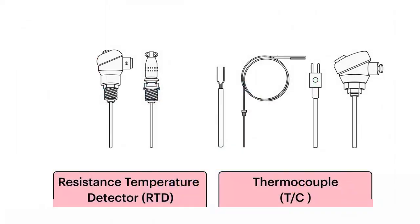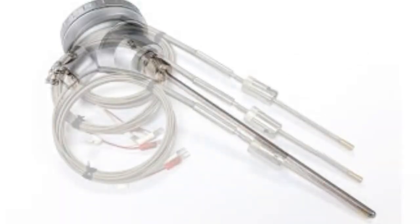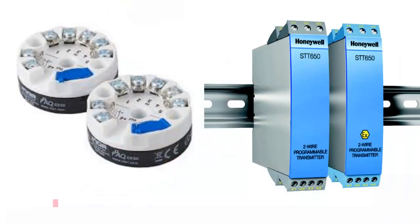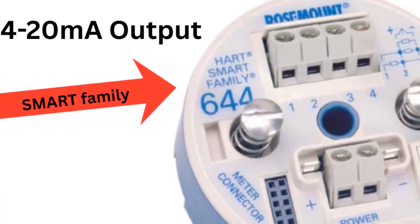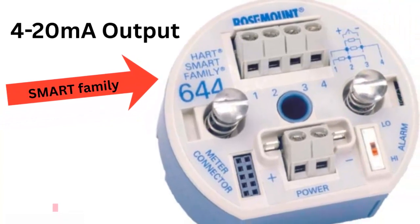Temperature transmitters take input from a sensor, usually an RTD or thermocouple, and convert it into a usable signal. RTDs are accurate and stable but limited in range. Thermocouples cover higher temperatures but are less stable. Transmitters can be head-mounted or DIN rail-mounted. Most output 4 to 20 milliamp. Smart units can auto-detect sensor type, compensate for lead resistance, and store calibration data.